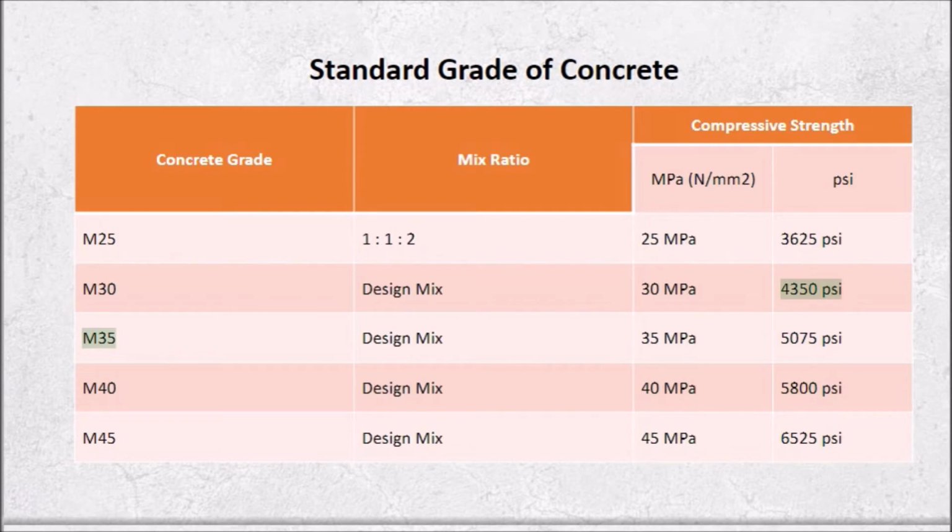M35, design mix, 35 MPa, 5075 psi. M40, design mix, 40 MPa, 5800 psi. M45, design mix, 45 MPa, 6525 psi.